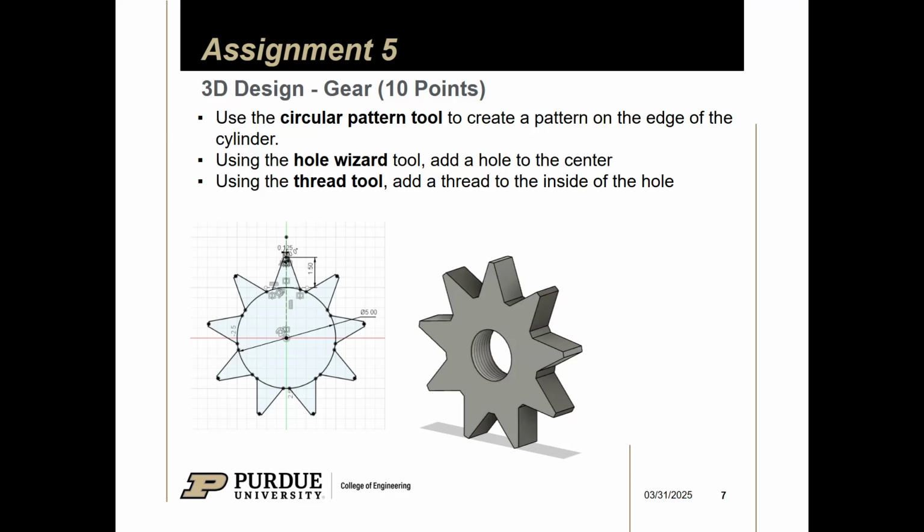So you want to make sure you can hand off a part drawing or design to someone, and they'll have as much information as they can to make your part the way you want it. And to do that, for holes, we really recommend you use the hole tool. That is mainly because it retains more information about the hole that you've created.